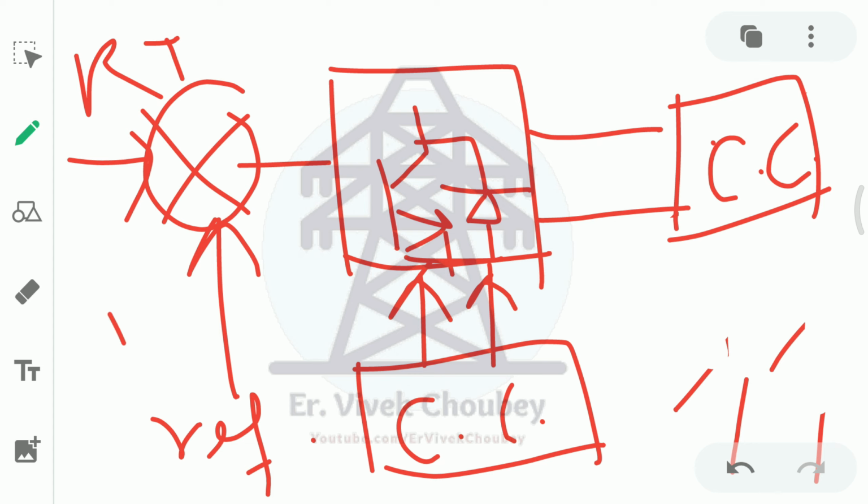Now if you can see that if there is a 1 milliamps of output from the comparator, that means the output is obviously low. That means the control circuit will trigger the IGBT at a slower frequency, and hence there will be a low average voltage that is applied at the compressor input. So if the room temperature and the reference temperature is same, then what will happen? The comparator will send no high output, and because of that, what will happen in a non-inverter AC, that it will turn off the compressor.